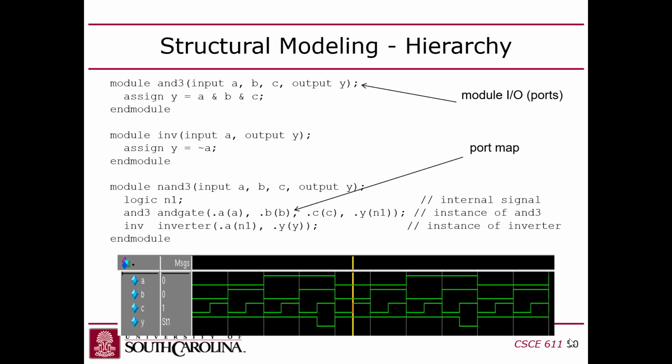That's why we're going to wait. Usually in a simulation, you have a test bench, which is another Verilog module that is in charge of driving the inputs and checking the output correctness. But in this case, this simulation was me just manually setting these inputs, and then watching the circuit drive the output in response.